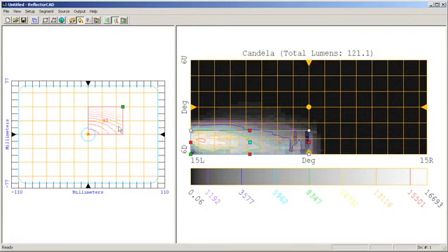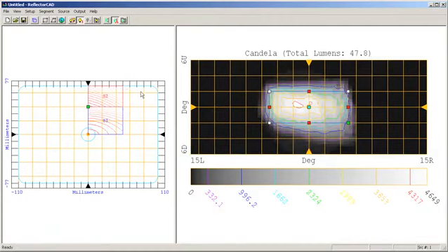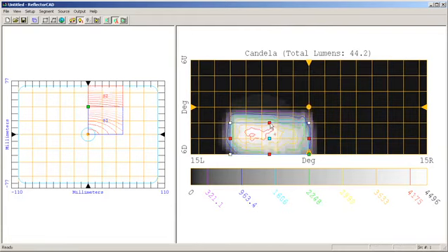Now, in the segmented area of the display screen, you will see a series of contour lines in the particular segment. What this indicates is whether this new segment is above or below the base surface that you've identified. We're ready to insert our next segment. I come up to my segment button, and I'll begin creating my new segment. And we'll see that the luminous intensity pattern from that particular segment with the source that I've defined now appears over in the output window. Once again, I will be able to take this luminous intensity segment and move it and reshape it to my desired output, and ReflectorCAD will automatically update that particular segment.